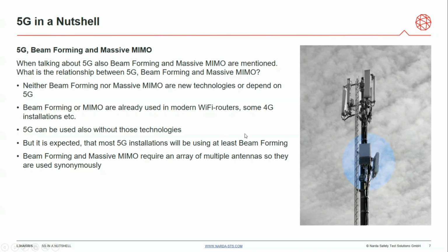But so far it was only used either to double transmit a signal, so to increase the quality, or to double the capacity by sending other signals over more than one antenna. But on top of this MIMO for diversity, there is now also the function of beamforming, which is being added, so that by electronic forming of the beams, it is possible to send more power, more energy to a certain position in space to have a kind of spatial multiplexing.